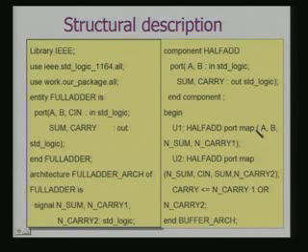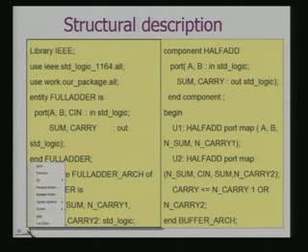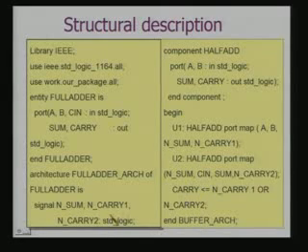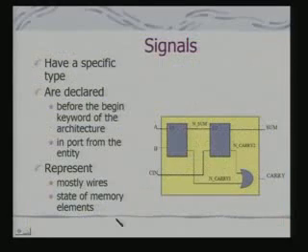So what it is doing, A, B, and I have got N sum, N carry and this C in and N carry 2. So these are doing a port mapping. Why is this port mapping required? This port mapping is required because if you look into here, this is the connectivity that I want to represent. The C in goes to here, okay, and this output here should come at this point, okay. So this is what the structural description is all about.